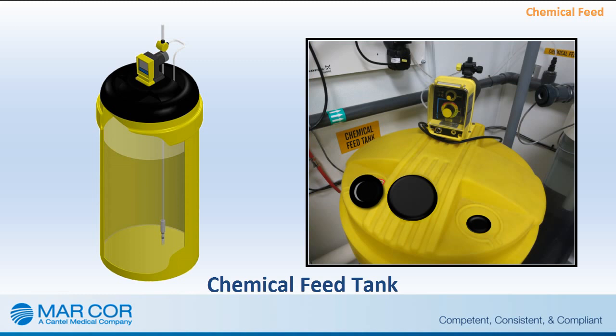Some facilities increase the pH of the water in order to minimize leaching of lead and copper from piping. Carbon tanks and the RO don't function well if the incoming pH is too high. If needed because the incoming pH is too high, a chemical feed pump can be used to adjust the pH of the feed water by dosing small amounts of chemical into the feed water. The most common chemical used is sulfuric acid.